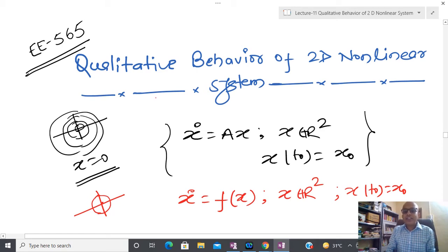Whenever you talk about stability also, please do not say that some nonlinear system is stable. Emphasize that the nonlinear system is stable about a certain equilibrium point, or unstable about a certain equilibrium point. In the case of a pendulum system, you have already seen that one equilibrium point is stable and another is unstable. So saying that a pendulum system is stable is meaningless. You have to be specific whenever you write papers or give talks, so please specify that point. Now I think that point is clear to you.